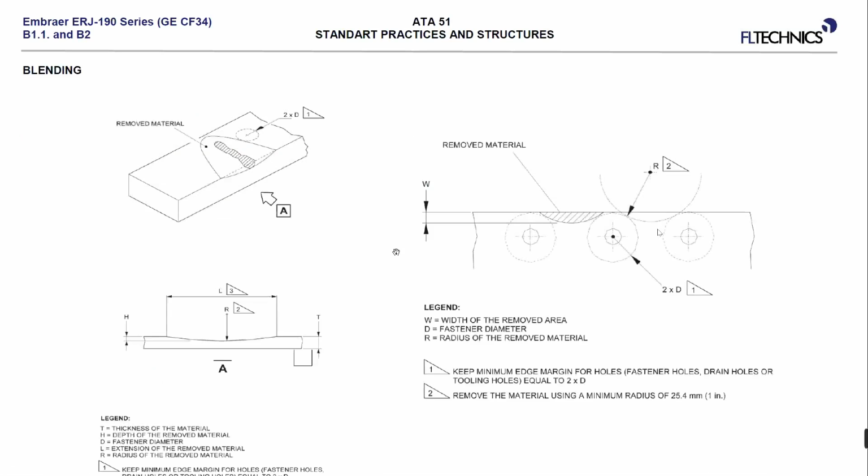Okay, so you have the finding with your damage. Check what type of damage you have. Check the exact location. Check for allowable damage. And then, if necessary, do some blend out, do some rework, maybe apply some protection. Many times we just have small, minor dents, but still you have to put them in the book.